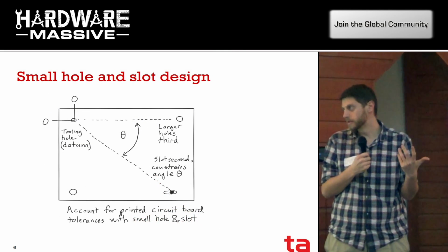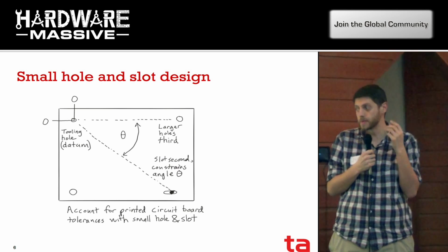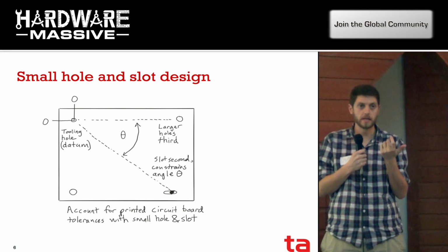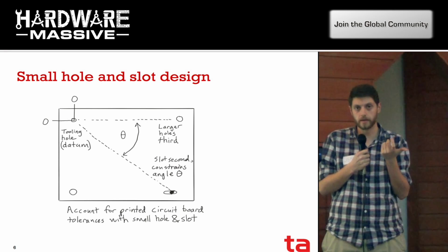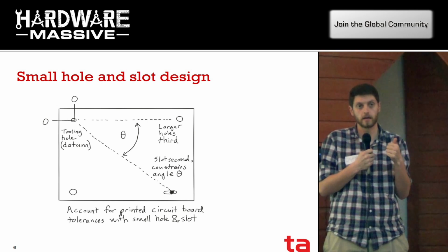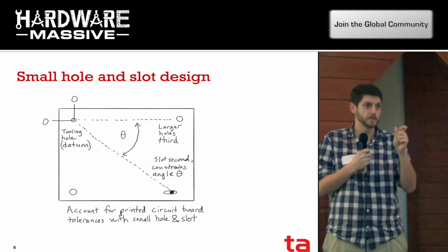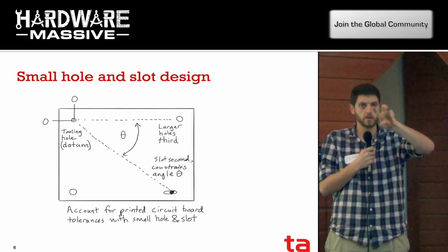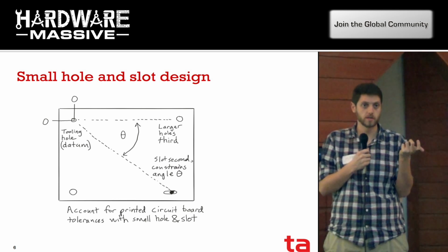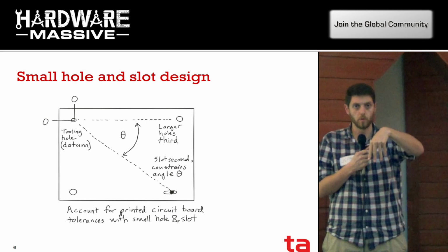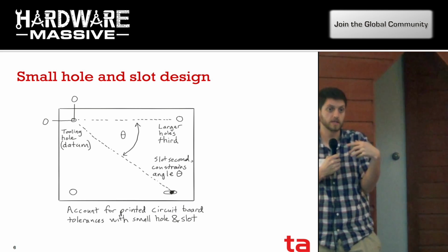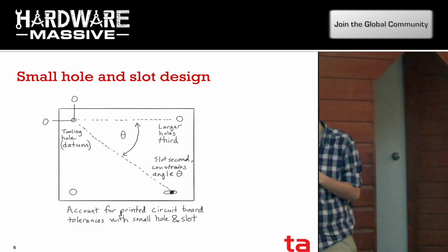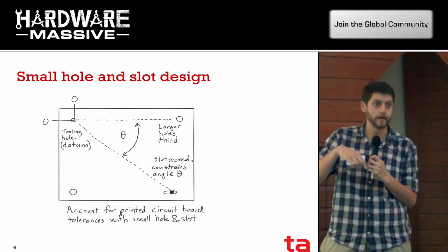One notion, some ECAD 101 that might be non-obvious if you spend more time on the electronic side, is that it's very easy to design your board in such a way that the mounting of it is over-constrained. With tolerances on holes for a product, if the tolerances line up such that things are out of sync, then very easily you're in a situation where you can't install a board into the screws or whatever mounting device you were hoping for. One way that you can prevent that over-constraint is the introduction of a slot, as a way to give you a little play along a given dimension.